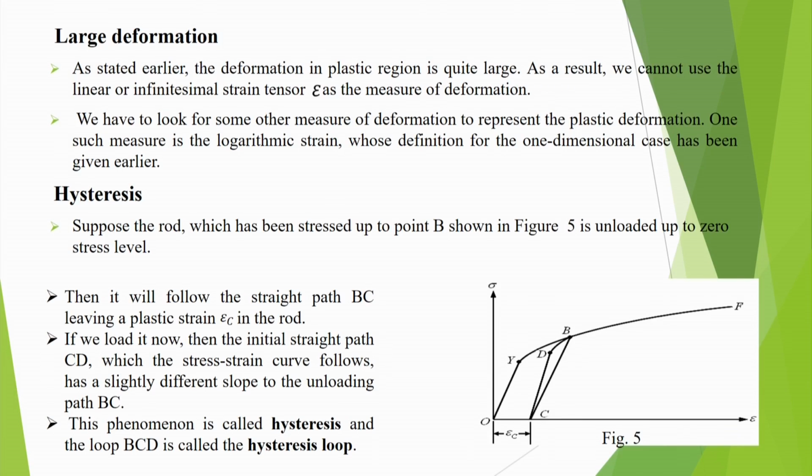It may be of the order of 1 or more. In that case, our normal infinitesimal strain measure is not valid. The way we have been defining strain in elasticity is not proper. So, we have to use a different measure, like the logarithmic strain measure, or the true strain, or the natural strain. This point has to be kept in mind.